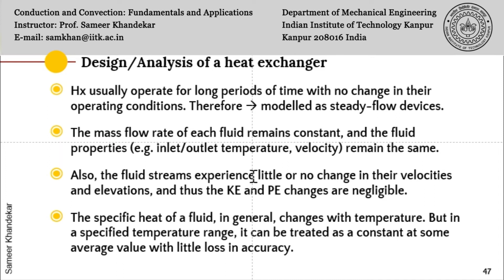Then the fluid streams experience little or no change in their velocities and elevations, and thus the kinetic energy and potential energy changes are also negligible. So this is also a common assumption under which we will do the following analysis. Then the thermophysical properties like specific heat of the fluid in general change with temperature. We all know that. However, sometimes the temperature change may also be large, but for a given range, it can be treated as constant at some average value with little loss of accuracy. So for most analysis, we will assume that the thermophysical properties are constant.